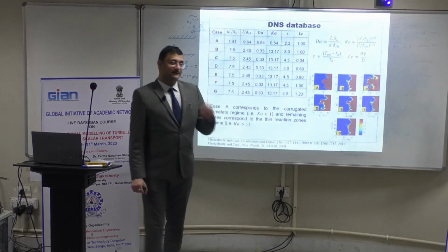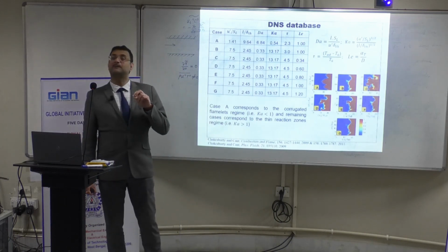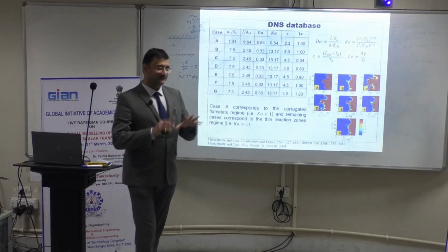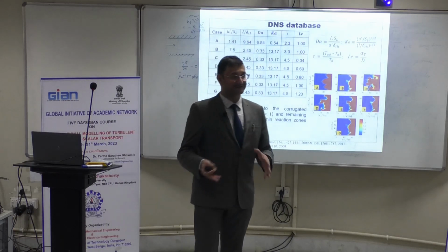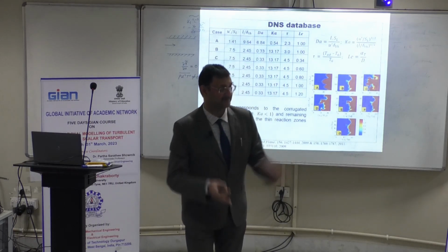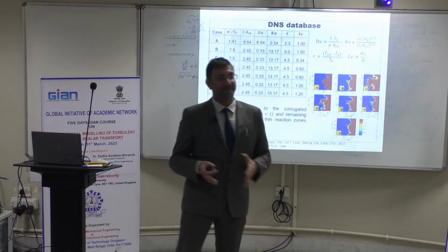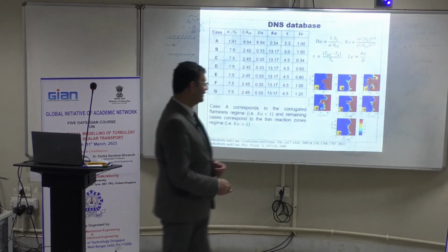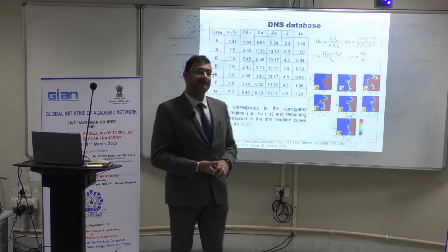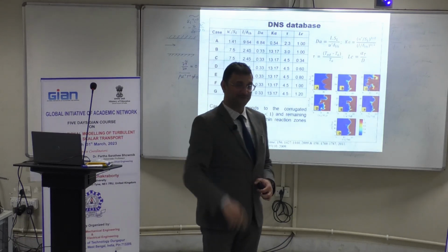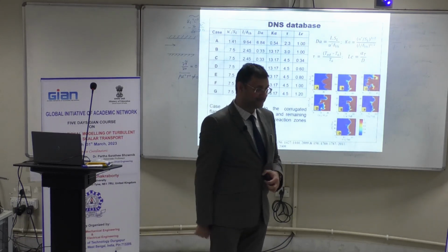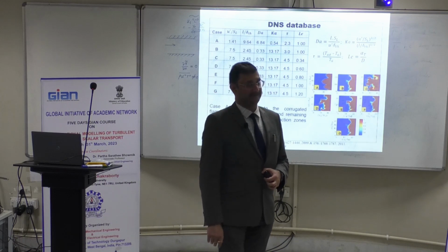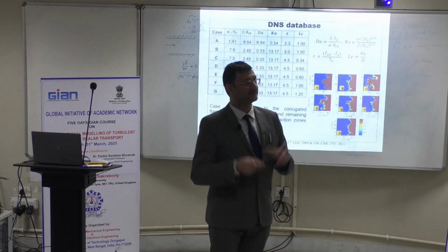That's why, if somebody thinks that you have designed a combustor based on conventional hydrocarbon fuel, say a burner designed for stoichiometric methane in a mixture which has a Lewis number of 1, and suddenly I take that burner and put hydrogen in that, because we are moving towards the hydrogen economy, and it will give you the desired performance, it's not going to happen.